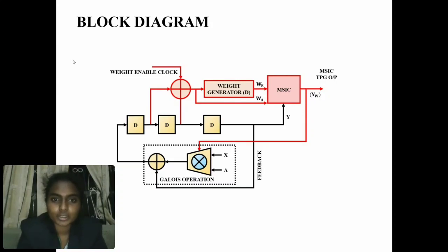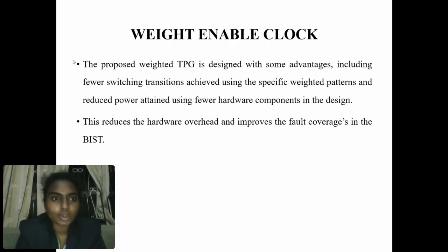It consists of the weight-enabled clock, weight generator, Galois operation, MSIC, and MSIC TPG output. Weight-enabled clock: the proposed weight-enabled clock is designed with some advantages, including fewer switching transitions achieved using the specific weight pattern, and reduced power attained using fewer hardware components in the design. This reduces the hardware overhead and improves the fault coverage in the BIST.